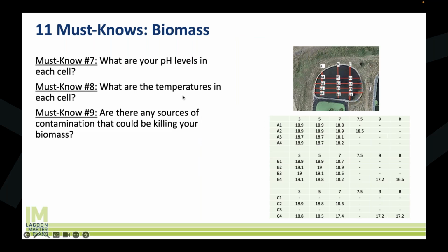Biomass. So 3 things on this. Your lagoon is a biological reactor, which is cool to think about. Everybody thinks reactor sounds really complex, like you've got a lot of moving pieces. Not in a lagoon. What impacts this are your pH levels, number 1. If you are too alkaline or too acidic, both the type of bugs that will grow, and the rate at which those bugs will consume the contaminants in the water are going to be impacted.